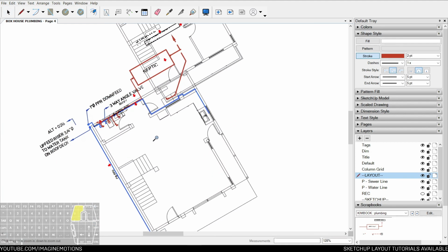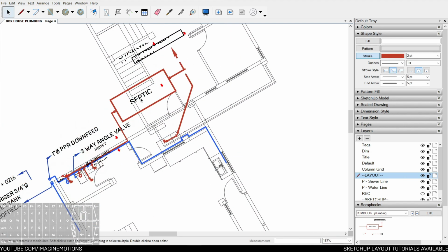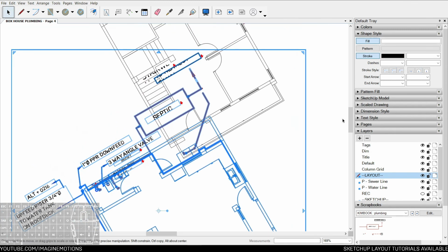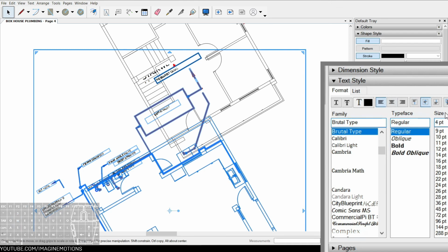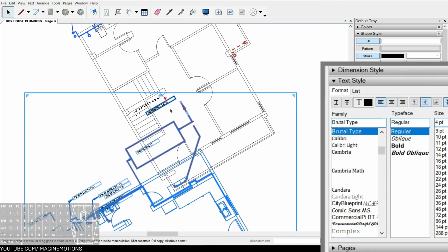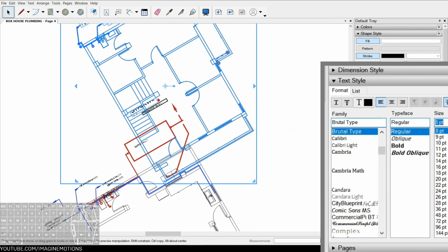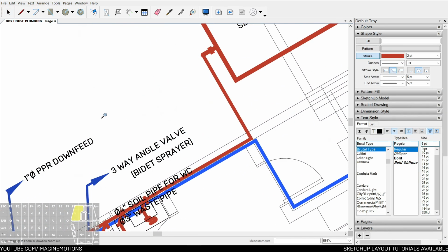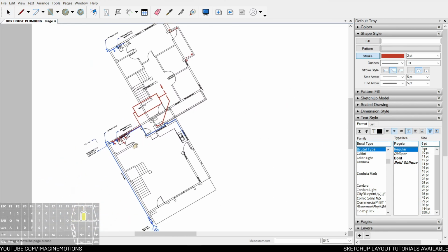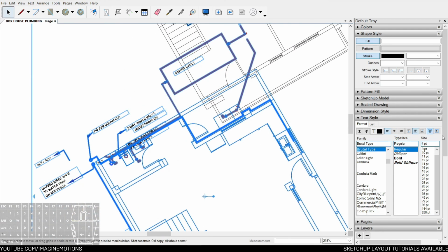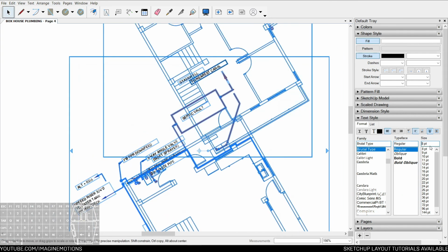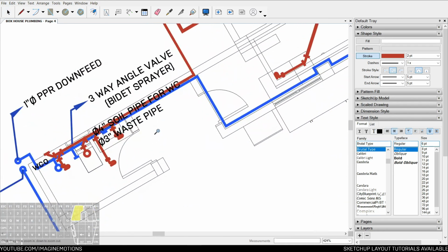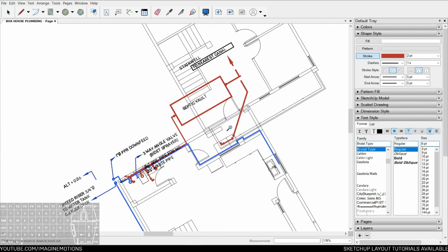And then let's try to see the text that didn't become smaller. Go to text style and make them maybe 4 points, unbounded, so as the other side. You have to make sure they are still readable on towards the blueprint. So you can keep experimenting until you get the right size that you want to achieve. There.